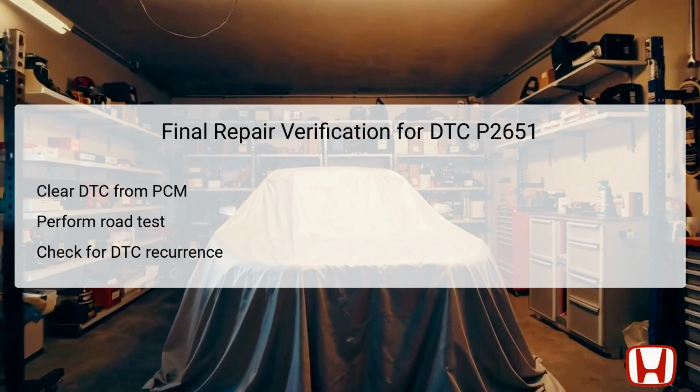Next, conduct a thorough road test to assess whether the repairs successfully eliminated the underlying issues. During this test, pay attention to engine performance, any warning lights, and abnormal noises. After the road test, check for any recurrence of the DTC, ensuring that the vehicle operates correctly within normal parameters.